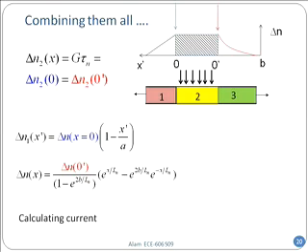By the way, where are those electrons going? They are recombining with the holes, and the holes are being pumped through the contact. So in fact, in the green region, holes will flow in to support the recombination of the electrons. As every electron is moving in, holes will flow in, and therefore the current will flow. Because in the circuit, whatever electron gets out from one side, that must be balanced by the hole current from the other side. Okay, now do you see how to calculate delta n? Delta n is already known at x equals 0 and x equals 0 prime. That is the interface between the magenta and the yellow and the green, right?